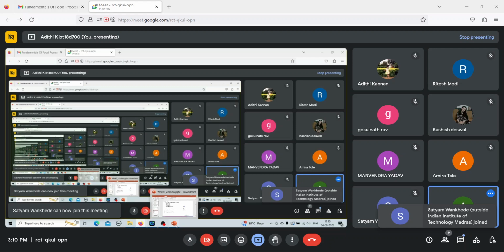Thixotropic fluids show decrease in both shear stress and viscosity at a constant shear rate over time. So it is where the viscosity and the shear stress decrease with time. It's not just one decreasing, both of them decrease with time, and hence statement 1 is false. Statement 2 is also false because bentonite clay becomes harder. It becomes more viscous, or more resistant to flow, over time.